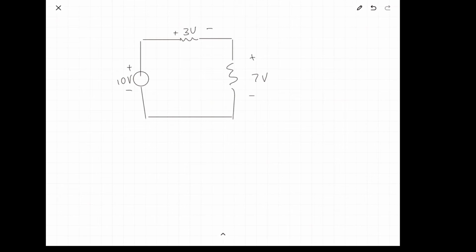Now that we've got the explanation out of the way, I'd like to show how I'd actually solve Kirchoff's voltage law around this circuit. So firstly, I wouldn't actually have to pick a 0 volt point, but what I do need to do is have a loop and have it with a direction. So I draw a loop with an arrow on it. Now, I start my equation, 0 equals.